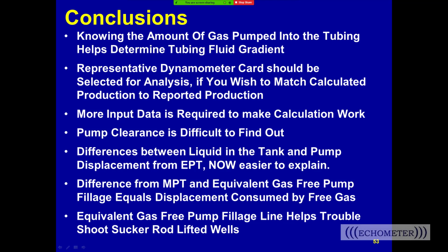And possibly in a few wells in the world, the pressure across the pump may not be constant during the upstroke or during the downstroke, and that could cause a changing load. Like the bottled up pump, the pressure goes way up, and then it appears to drop off after the flow begins. Okay.